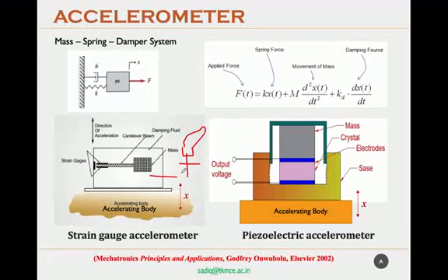Now let us see the construction of a piezoelectric kind of accelerometer. The construction is here. What you see is an accelerating body. There is a casing, that's a base. The base is attached with the accelerating body. There is piezoelectric crystal here.